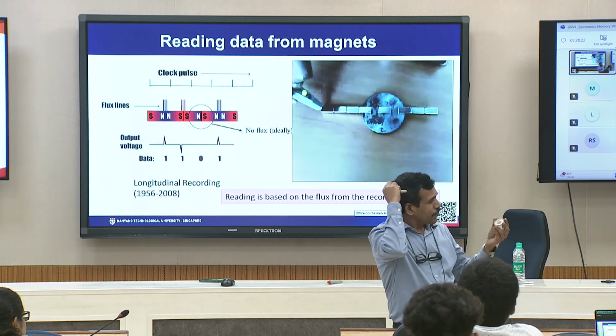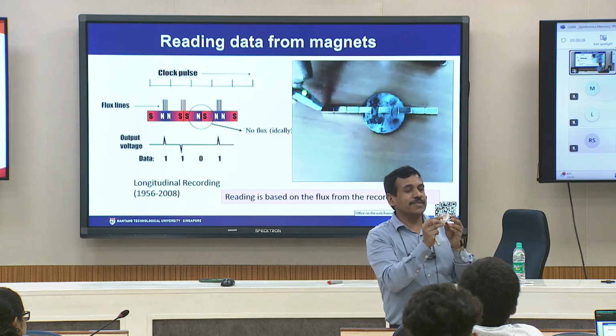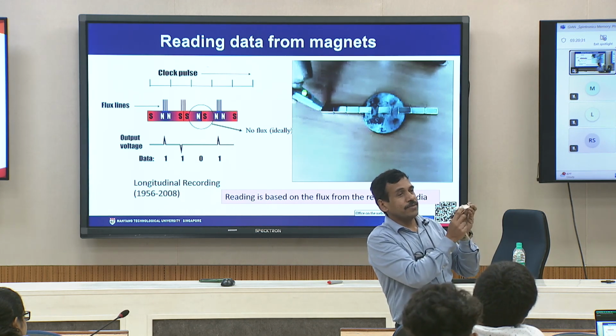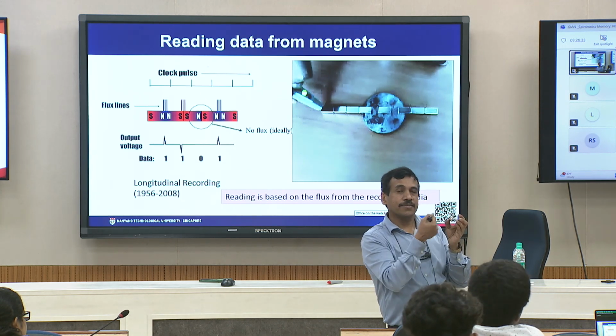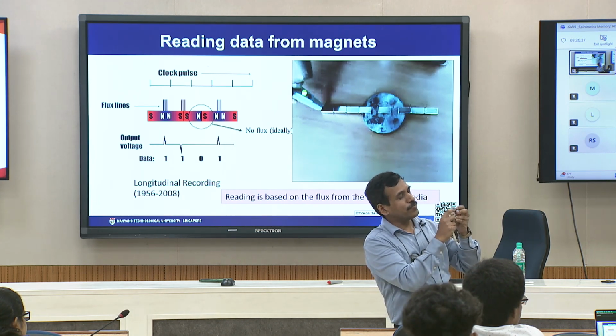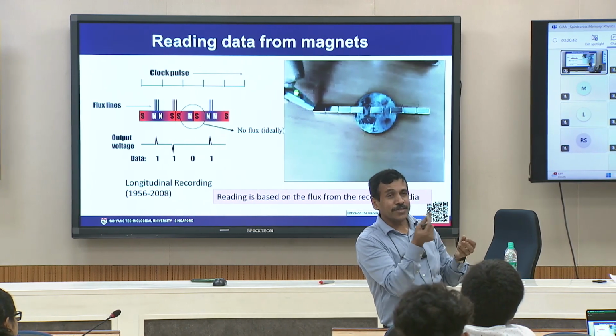Secondly, we learned about the target and magnets below the target. In this case I am showing you a target and the erosion profile. Here we have symmetric magnets. Because the magnets are symmetric, you can see a large portion of this target is eroded and we cannot use it anymore.